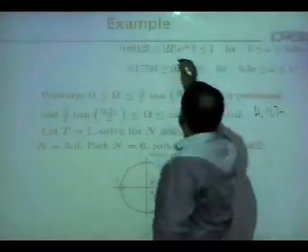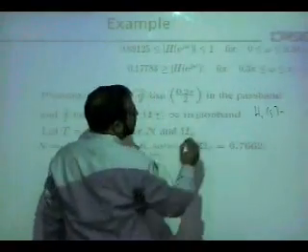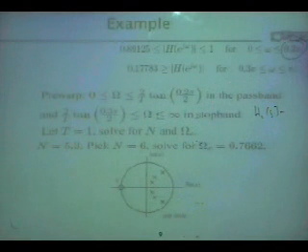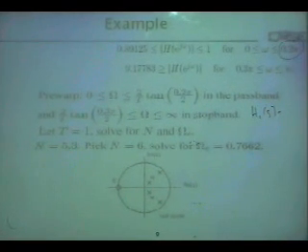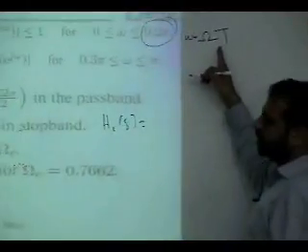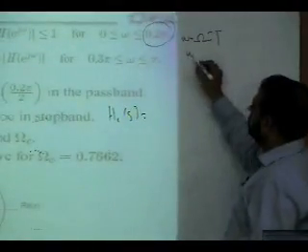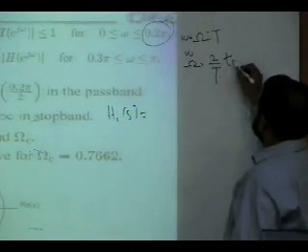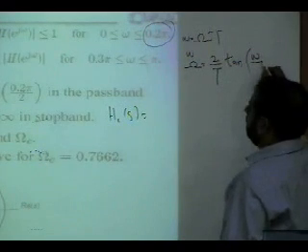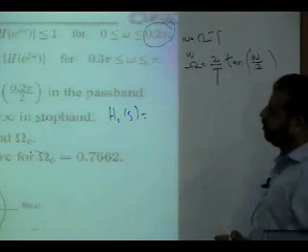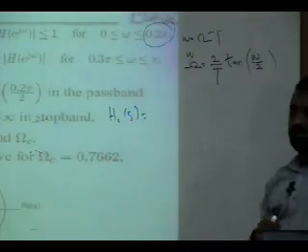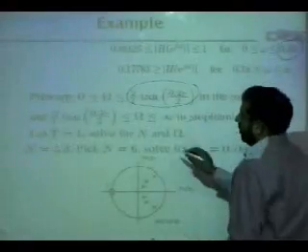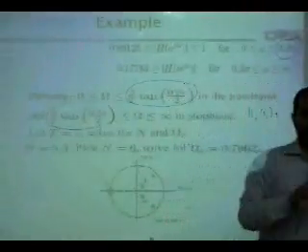Now to convert the 0.2 pi, this frequency, into capital omega, you will not use small omega equal to capital omega into T. No. Now you use the formula which says capital omega is equal to 2 by T tangent of small omega over 2, or something. Yeah. So this is what you need to use. Okay. So the frequencies need to be converted using this, both the frequencies. Okay. So this is the only difference.